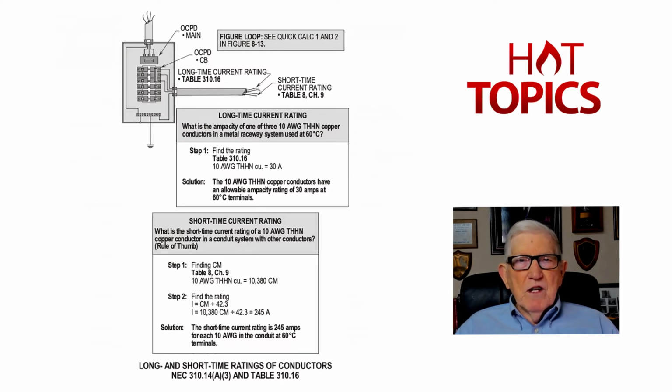So in residential, you usually find 60/75 C rated circuit breakers. And the reason for that, naturally, you can cable them at 60 degrees C ampacity, or pull conductors in conduit to, like air conditioners or larger pieces of equipment, and use a 75-degree column.